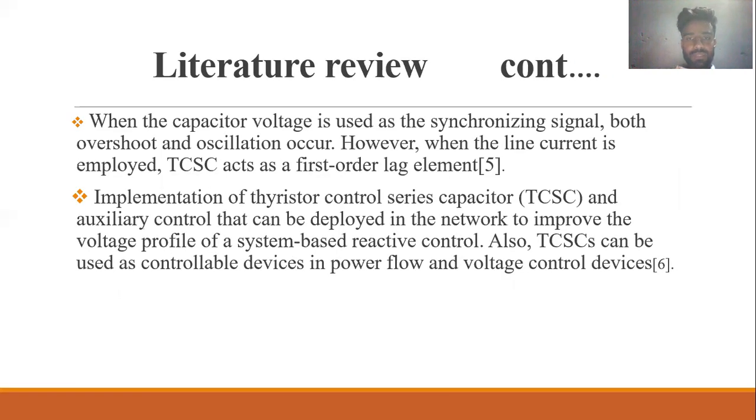In the next paper, we studied how to synchronize our capacitance with the voltage profile, because overshoot and oscillations also occur. By considering the line current as a reference, the TCSC acts as a first order lag element in our series compensation. In the next paper we studied the implementation of its controlling mechanism, how control is operated with a PID controller and a PI controller, and we did a comparison in this paper.